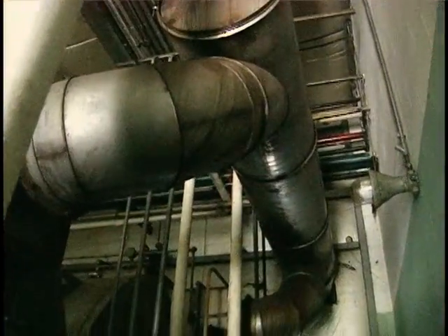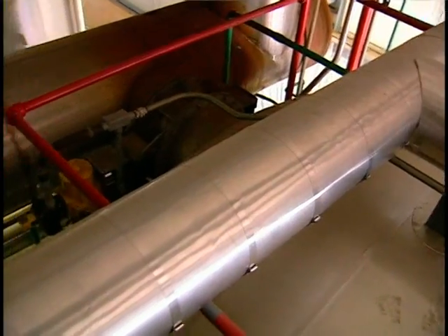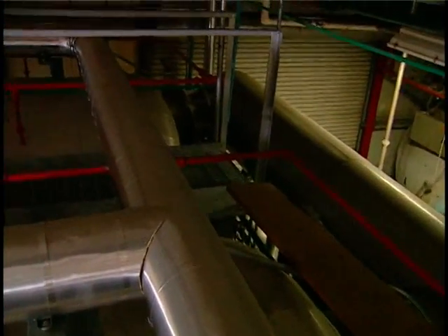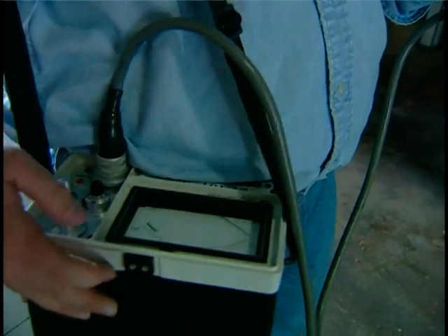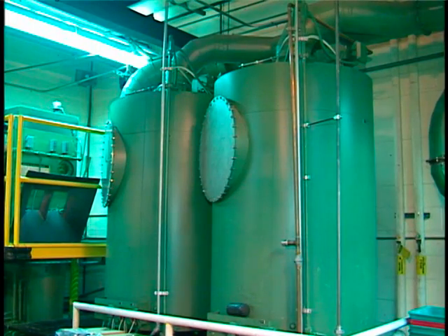The inlet concentration to the carbon adsorber should also be checked. Adsorbers designed to operate at 10 to 25% of the lower explosive limit will usually have an LEL monitor in the inlet duct to shut the system down if the concentration increases above this safety limit. Otherwise, the measurement will have to be made with a portable analyzer. Increased inlet concentration could lead to breakthrough unless the regeneration frequency has been increased.